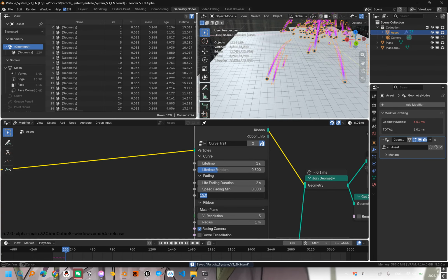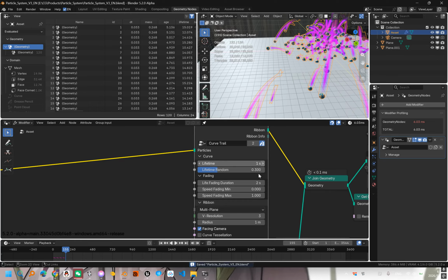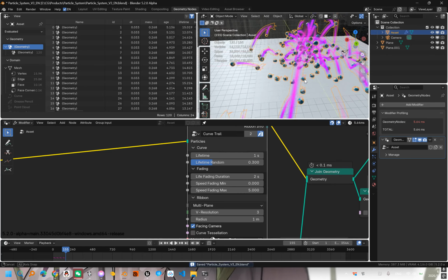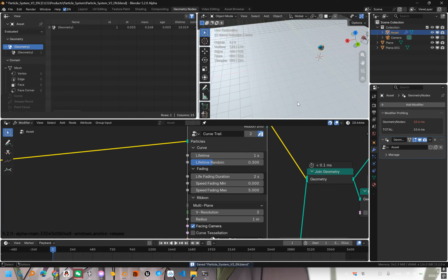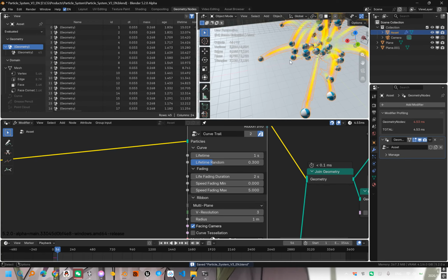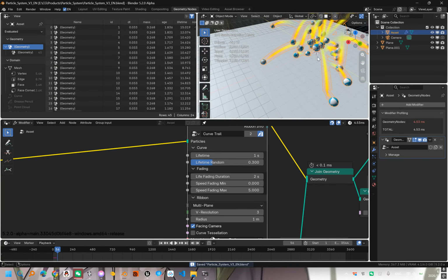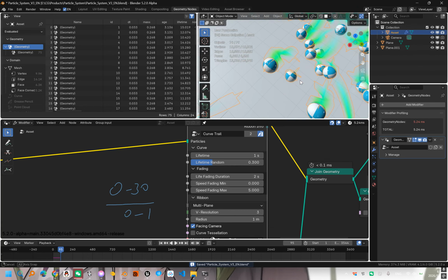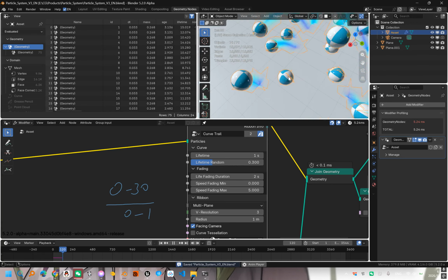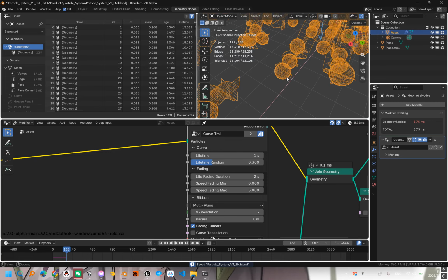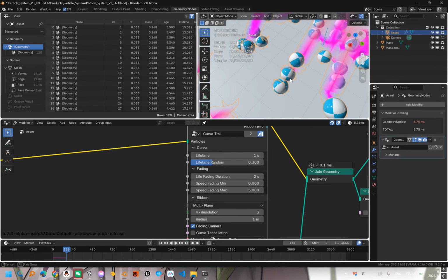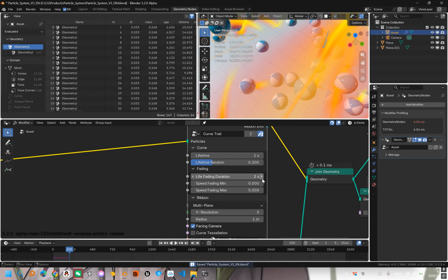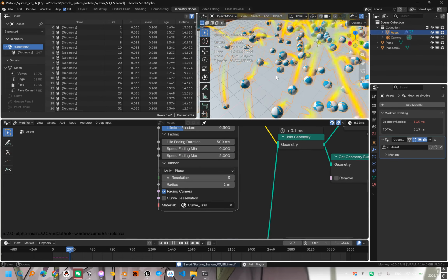So you can just set it to 1 in case your particle has something pretty low here, for example 5 seconds. Other particles will have a very long trail, but for a particle that is not moving quite a lot, it will just get a very short trail, and also have a left fading. So once the particle is dead, it will be fading out here.